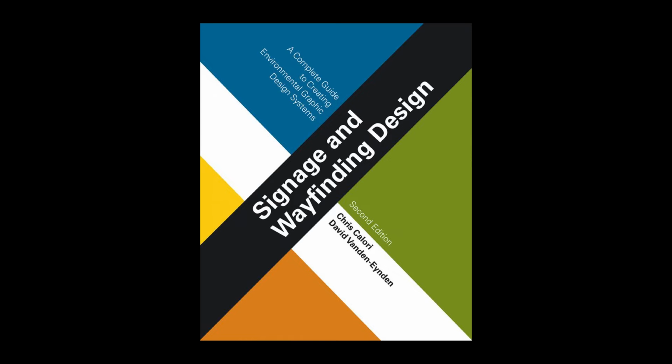Internal illumination. Internal illumination refers to light that is transmitted from within a sign. See Figures 6.26 through 6.32. It is commonly used for signs in both exterior and interior environments. As such, internally illuminated signs can take several forms, the most common being a rectangular sign box with a translucent plastic face on which the graphics and background are completely backlit, increasingly by white LED lamps, which are rapidly overtaking fluorescent lamps as the light source.